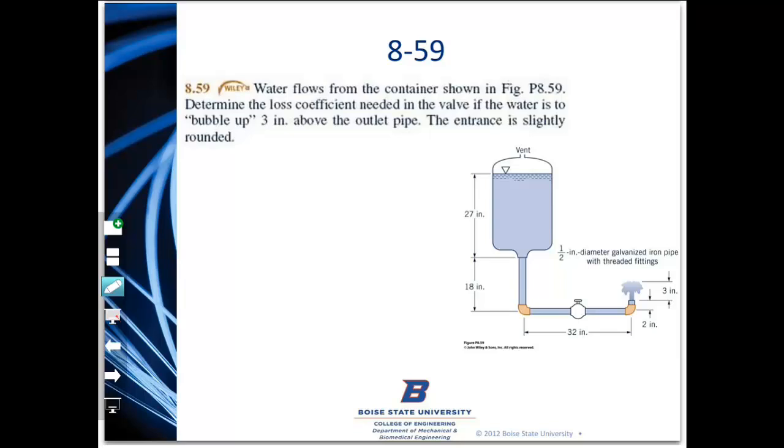Okay, so water flows from the container as shown. You're asked to determine the loss coefficient needed in this valve right here if the water is to bubble up 3 inches above the outlet pipe. The entrance is slightly rounded.